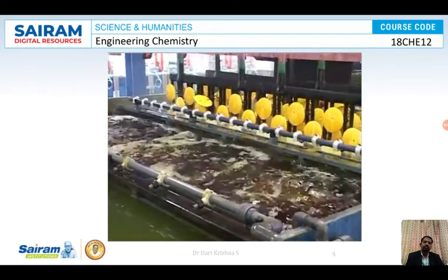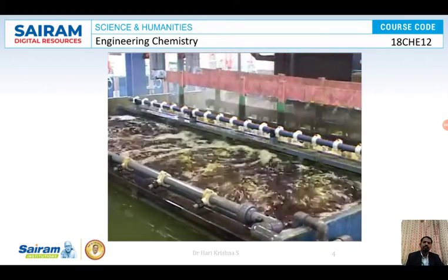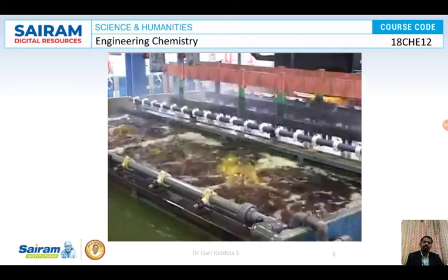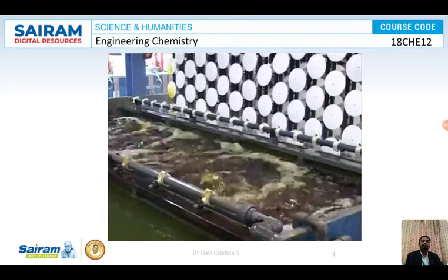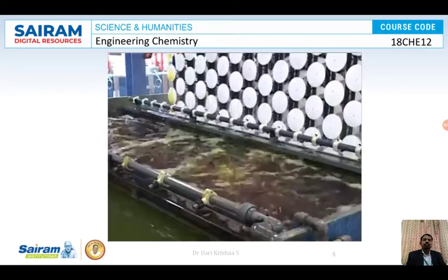After etching, parts are thoroughly rinsed with water, then neutralized in a chemical step that reduces hexavalent chromium to trivalent chromium, since traces of the former will poison the catalytic process.